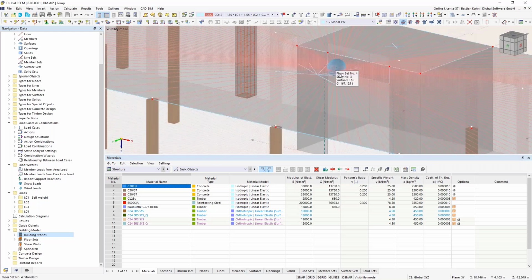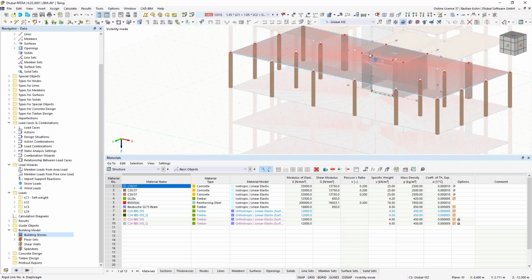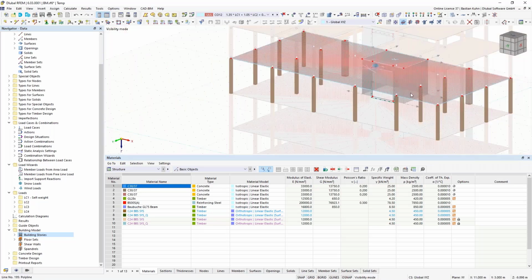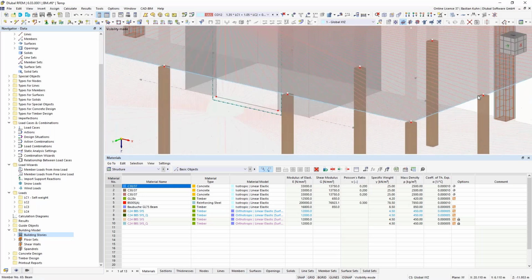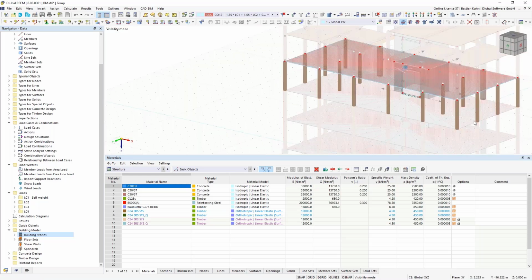So you see they are all centered in here. There are the surface cells. They are only on these smaller objects in here. And now each of these points is connected rigidly with the center. Not completely rigid, as the ends of this rigid coupling have a moment hinge, and that's also the reason why I did not define moment hinges on the columns in here, as the ceiling itself is considered as a ceiling. It may sound a little bit stupid, but that's an important point.